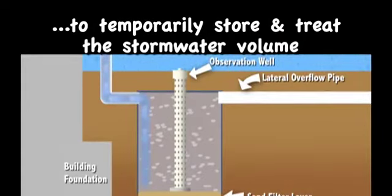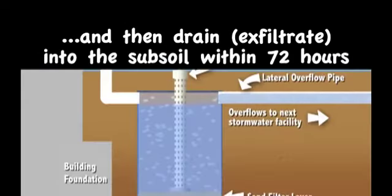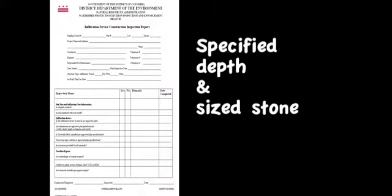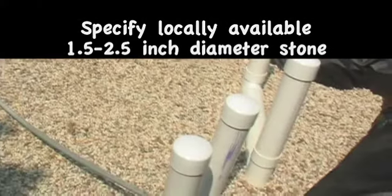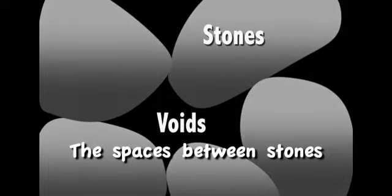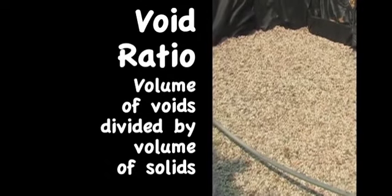It must be able to capture the first half inch of stormwater, then release that water into the subsoil within 72 hours of the rain event. The infiltration device should be filled with stones from 1.5 to 2.5 inches in diameter. When placed in the infiltration device, the stones leave empty spaces between them. These empty spaces are called voids. To determine the storage space available in the stone-filled infiltration device, we must know the void ratio.